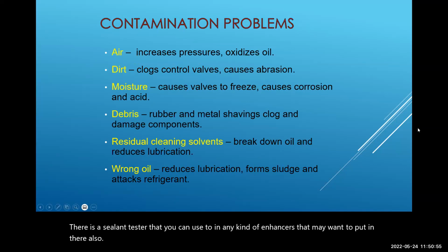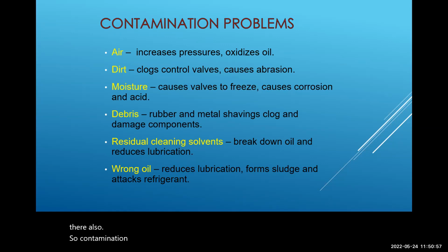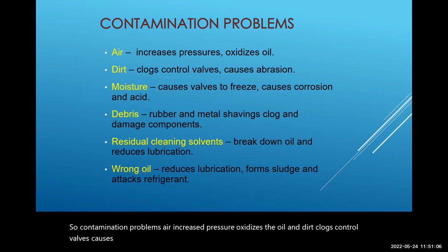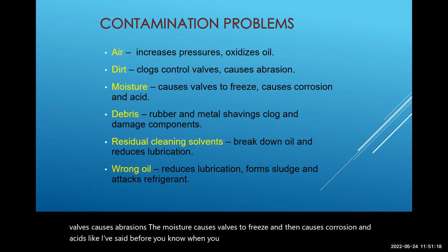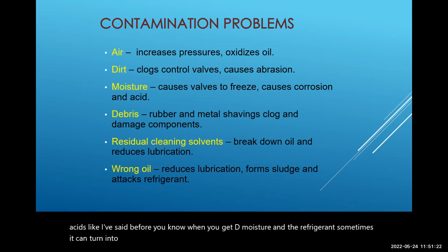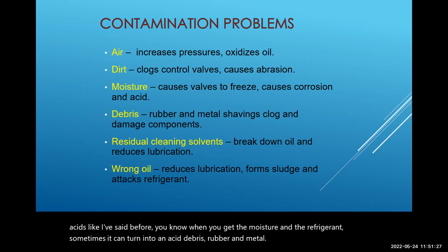So, contamination problems. Air and increased pressure oxidizes the oil, and dirt clogs control valves and causes abrasions. Moisture causes valves to freeze, and then causes corrosion and acids. Like I've said before, when you get moisture in the refrigerant, sometimes it can turn into an acid. Debris, rubber and metal shavings clog and damage components.